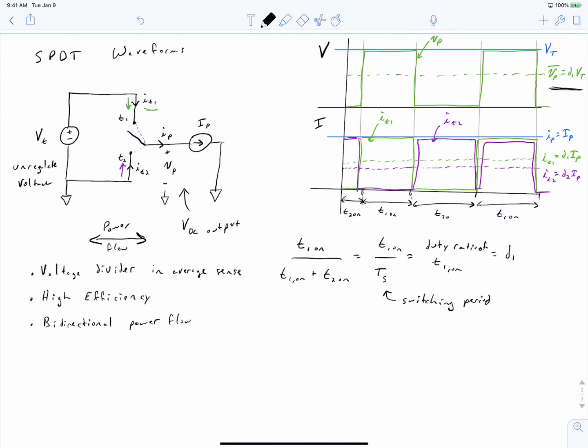In this video, I've introduced you to a new approach to voltage conversion. In this approach, we take a DC voltage source and we chop it up into a square wave voltage. We vary the pulse width of our square voltage waveform to achieve a desired average output voltage value. This is called pulse width modulation, and the energy conversion approach is referred to as switch mode electronics.